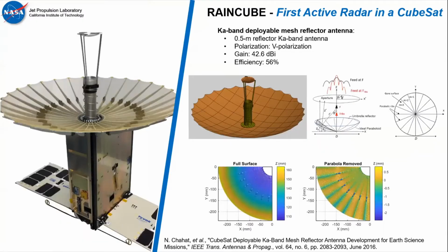The second thing that's important when you are an RF designer is to try to find a good balance between the complexity of the mechanical design and achieve the highest RF performance that you can. But you don't want to impose constraints that are too harsh on the mechanical design, because otherwise the likelihood of being successful is going down. So you need to have a very good trade-off between mechanical complexity and RF performance. So in this case, we actually minimize the number of ribs. So the maximum number of ribs that we accepted was 30 ribs.